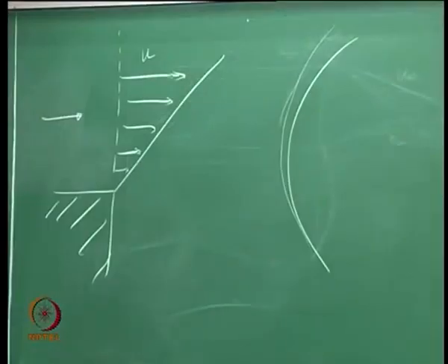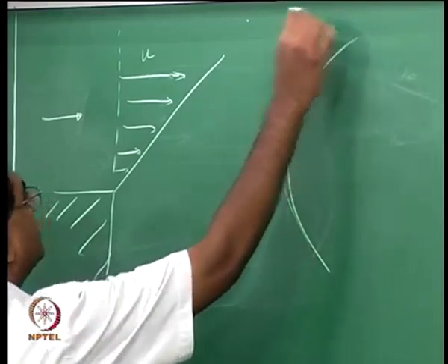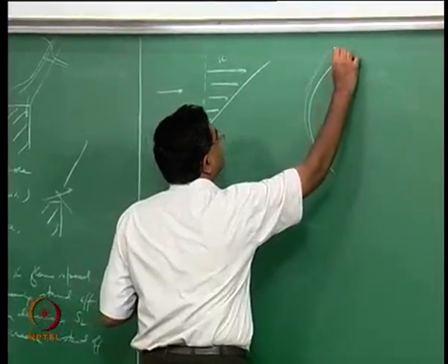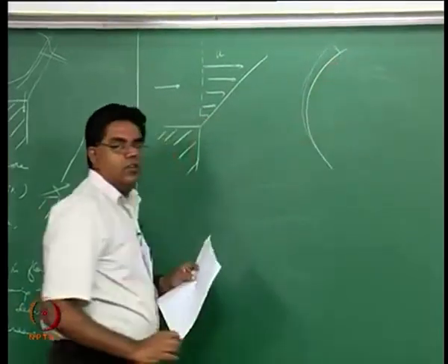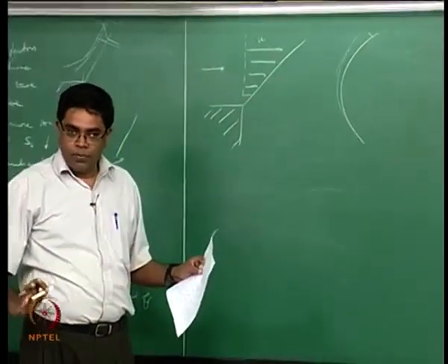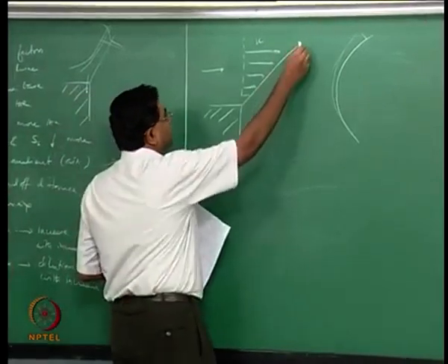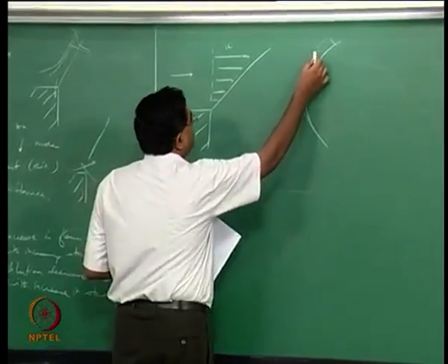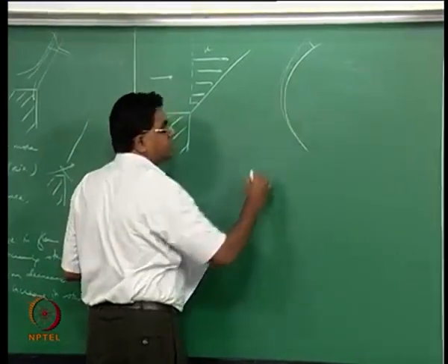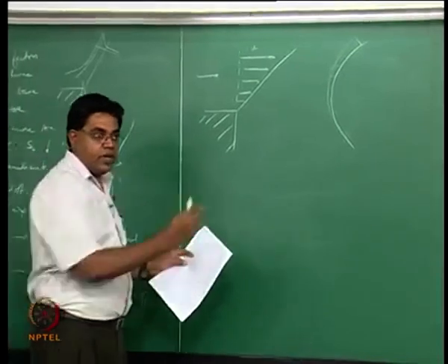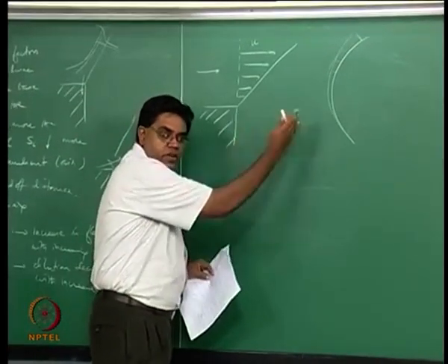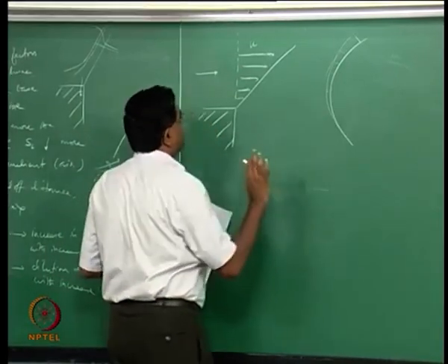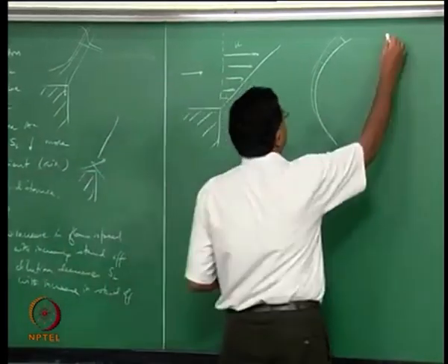As it is over here with respect to the free stream velocity, the flame speed is low, but the flow speed is actually decreasing linearly, and the flame speed is decreasing because of heat loss on the one hand as its proximity to the burner is determined, and because of the mixing, and we are now considering a fuel lean case.